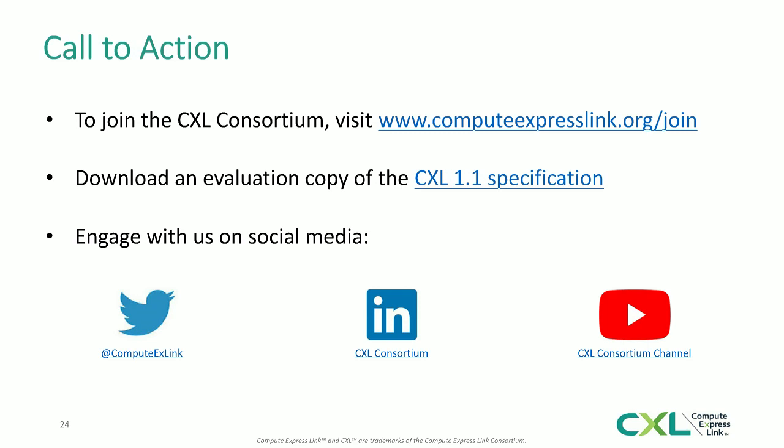Any thoughts on CXL link efficiency, for example, actual data rate versus physical link bandwidth? So I've seen some estimates. It obviously depends on how well your traffic packs into the various CXL flit types. If you compare with a PCIe DMA kind of application, your efficiency is lower than what you get on PCIe because this is cache line size transfers. For bulk transfers, your efficiencies can be in the 70–80% range. And that's okay because the data rates start at 32 gigatransfers per second.